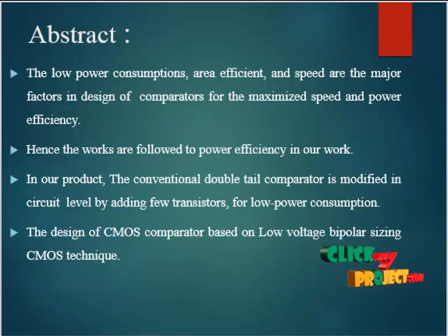In our process we can reduce the area and enable operation at low frequency, which would otherwise need large capacitor values. Then we implement the new DTC architecture, based on a voltage comparator, an integrator and a voltage digital to analog converter. To produce the desired delay, the inverted version of the input signal is integrated by the integrator to produce ramping signals.